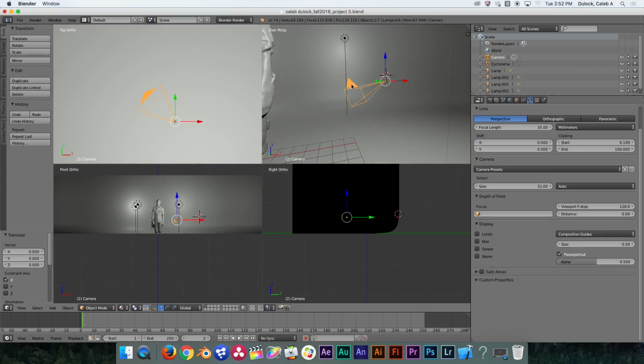Also, you need to know that the side that triangle is on is also the front of the camera, so that represents where the lens is located on the pyramid, this big open box. So that's where it views through. The shape of that also dictates the shape of the render area, which is always rectangular. And you may notice, of course, that the widget on the 3D camera is at the back of the camera for adjusting its position in 3D space.